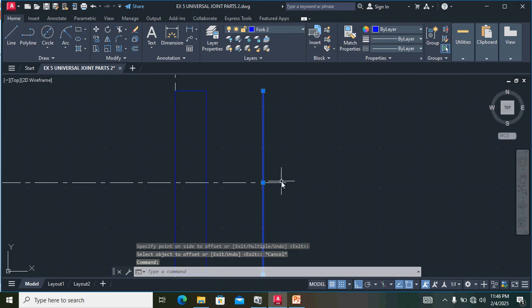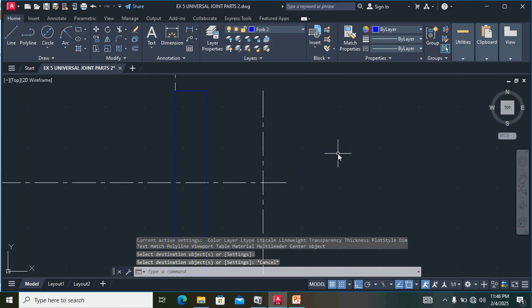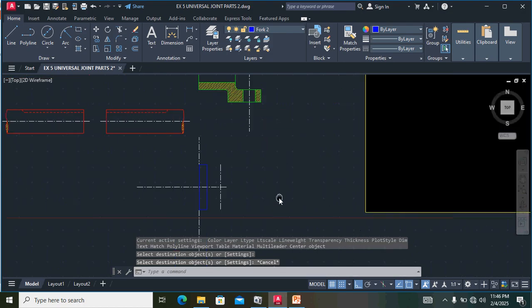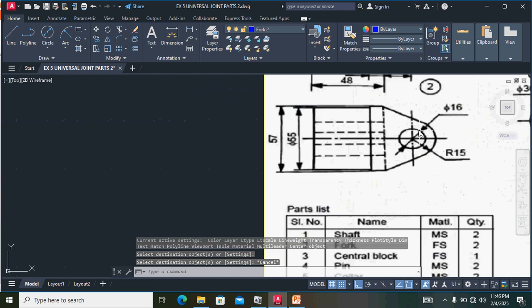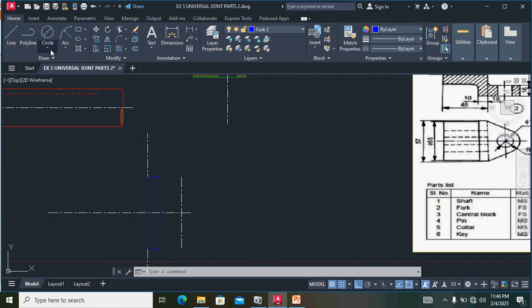So we go on to select the center point. We just escape. Correctly, we want to click the center point correctly. So we provide the radius. What is the radius of the circle? 15 mm. Okay, we provide the value 15. Type enter. Now we finish the circle.